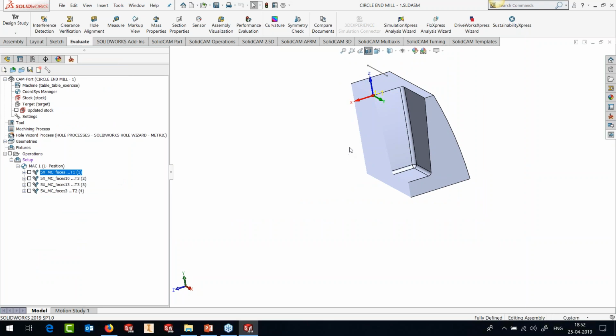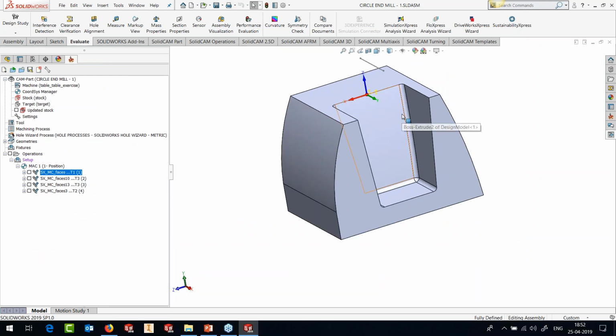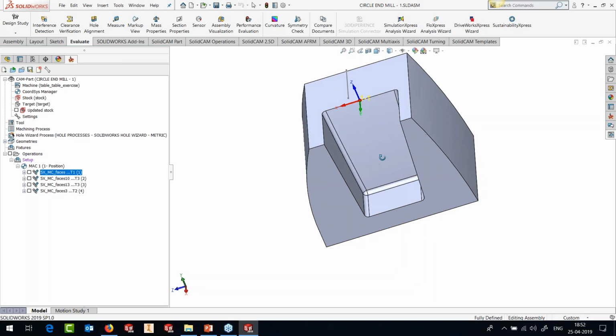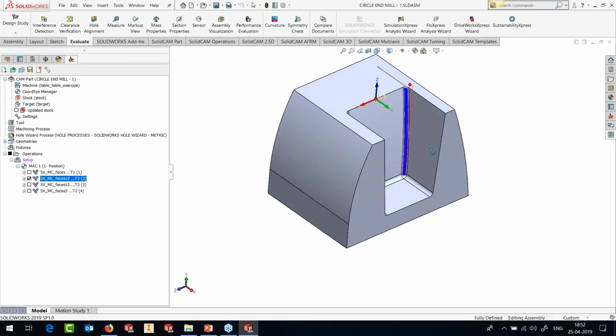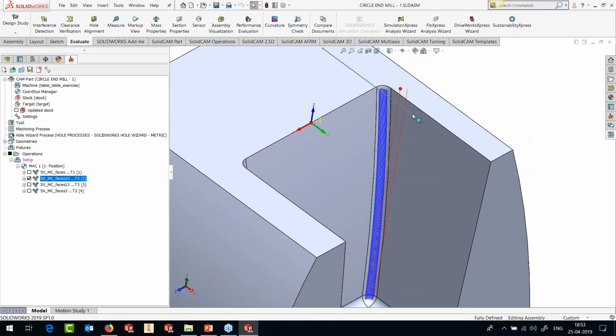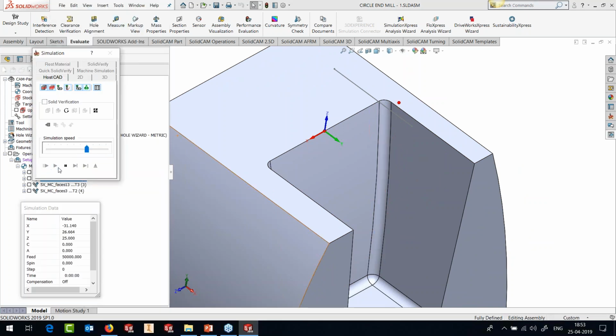Now, this is done by the software automatically, so you just need to define your starting contact point and your ending contact point, and you can get a very nice toolpath. Now, what happens to the fillets? You can use the same tool and generate toolpaths using morph between two curves. And what I have done here is I've simply defined two curves, and it generates a toolpath.